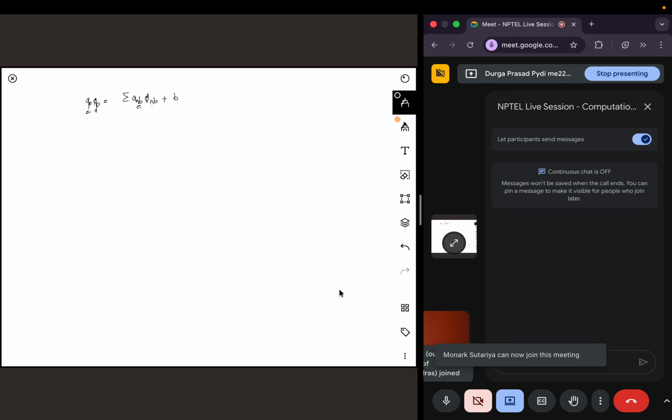So this set of equations we solve using, say, the Gauss-Seidel method or the Gauss-Jordan method. Like last week when we were saying, we can solve this as you start with an initial guess throughout, and all you have to do is let me just write this as pp n plus 1 is some relaxation times whatever you are getting, and this pp star you can get from Gauss-Seidel.